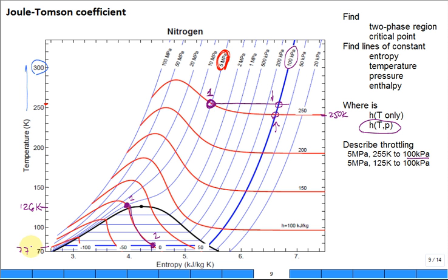77 Kelvin. That's what we call the boiling point for nitrogen at atmospheric pressure. The 100 kPa, boiling point, 77 Kelvin. So we see it really is cold. That's what we'd often expect coming out of vapor compression refrigeration. We studied vapor compression refrigeration. That's what we do. We like to drop it into the two-phase region and then boil.